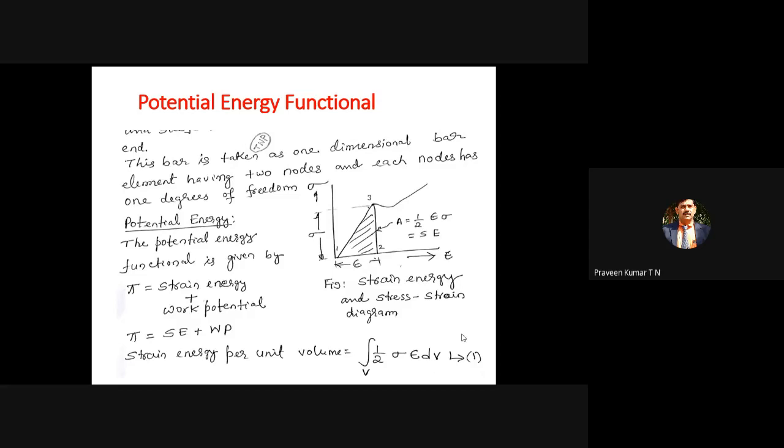Now, in the case of spring, that was concerned with strain energy; here it is heat energy. At room temperature the forging rod has lower energy. When the temperature is increased to around 500 degrees Celsius, the energy content increases. So your energy content is a function of many parameters. One is the temperature of the body, and the second one is the heat capacity of the body. Hence, your energy is a function of temperature and heat capacity. Heat capacity is nothing but what you call Cp.